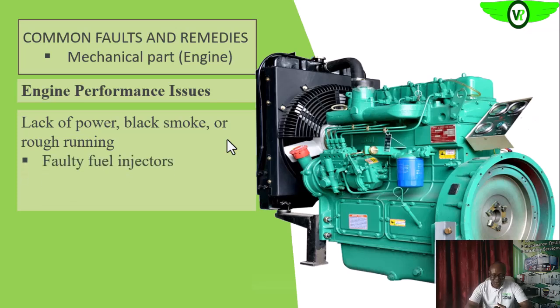So what could cause all of this? Of course, if your fuel system is faulty, it will affect the power that is delivered, because the amount of fuel that is delivered to the combustion chamber will be affected. So from the fuel pump through the injector, even your fuel filter, they are all suspects in this case. The injector nozzle that is delivering liquid fuel, not atomizing the fuel, with excessive fuel into the combustion chamber, can also generate black smoke. Are we getting it?